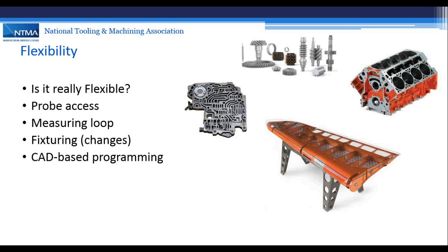Those are specific for the application and the part, whereas flexibility truly comes in when we look at part programming, and when it's CAD-based part programming, then we have the ability of what's built into the CAD to extract the manufacturing information, the part manufacturing information and tolerancing, and convert it over directly to the part program.